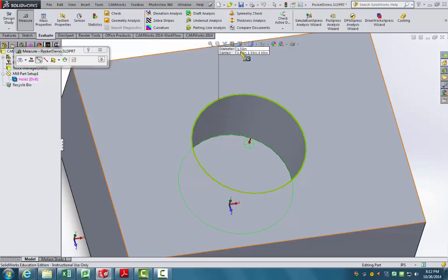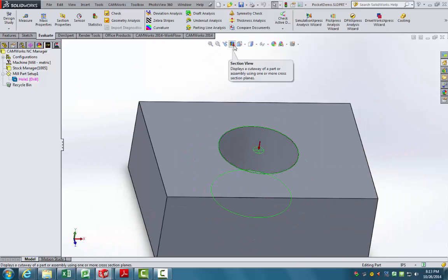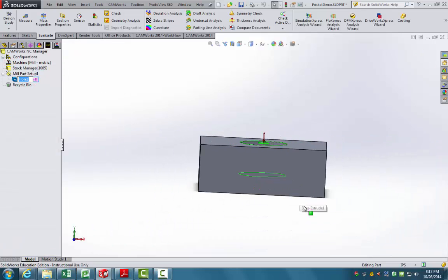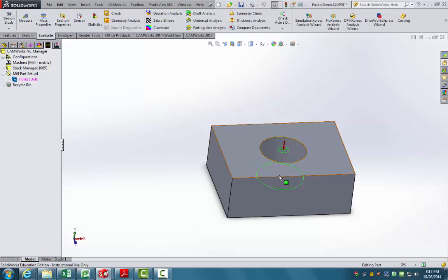That's a drill bit that you're not likely to find, and even if you are able to find a drill bit that large, it's not going to produce a very accurate hole. The other thing we can very carefully see, if I simply section the view, is that the bottom of this is a right angle. Most drill bits have an angled tip to aid in drilling a centered hole. Because of that, most of them can't do a right angle bottomed hole. So going back, we can clearly see that a hole is not the feature that we want to use.